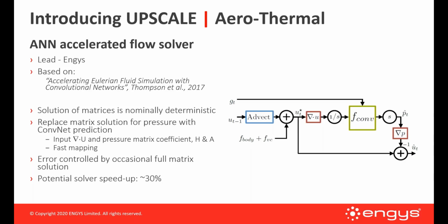So the first one is the accelerated flow solver, where we're a lead on. We initially started working on accelerating the fluid flow solver through convolutional networks directly inside the pressure solver. So the idea was that you create your normal algorithms for solving the flow, and then instead of solving a very expensive Poisson equation for the pressure, you use a neural network to predict, at least for some iterations in the cycle, the pressure or the velocity for the next iteration.